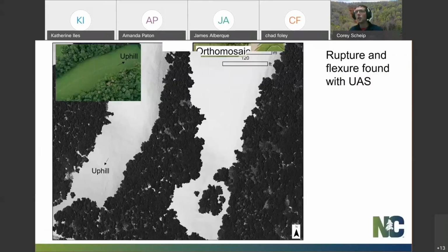We can do the same thing at another example location. This image you already saw on the top left, and you can see this linear break in the ground slope across the field. What I'm toggling here is a pre-earthquake LiDAR surface. This is a topography or elevation surface. And then I'm toggling on the elevation surface that we derived from the drone data.